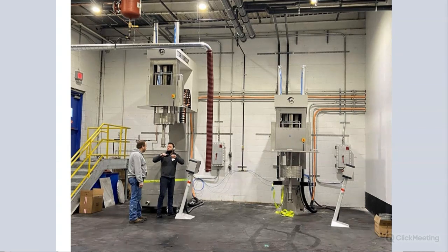Here you can see actually two production scale Dispermats, and they are really cool. What they are is basically a combination system, disperser slash basket mill all in one. The Cowles blade or the impeller blade is behind the gentleman with the gray sweater leaning against the blue drum, so they're not installed yet. But basically what happens is we first pre-disperse with the blade. That always stays on there, so don't take that off. And then when you're ready to do milling, you don't have to move the containers around. You just push a button on the control panel. The basket comes down, and then you're milling.